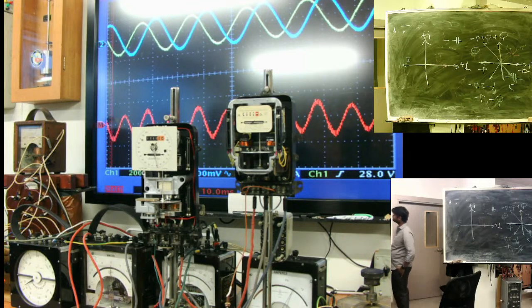And here is the opposite. You see? You supply active, and consume reactive. Yes. You take reactive from the net. It will be the second quadrant. It's like this.